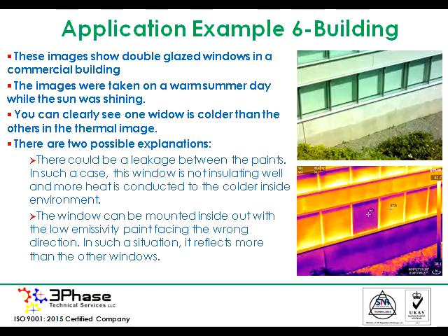Second, the window can be mounted inside out with the low emissivity paint facing the wrong direction. In such a case, it reflects more than the other windows. So it is not warming up but reflecting the cold sky.